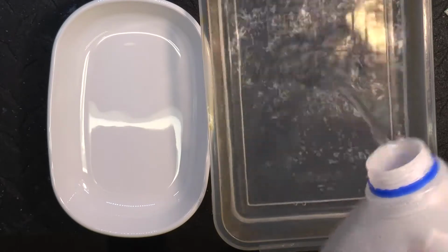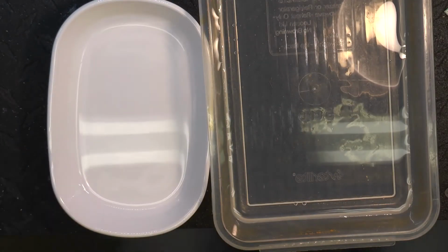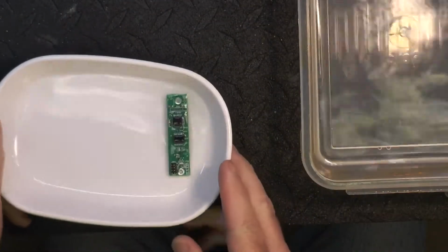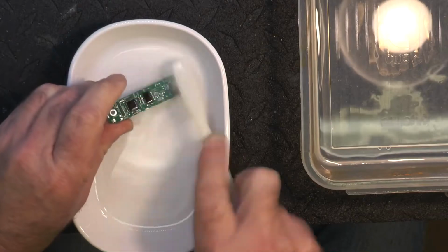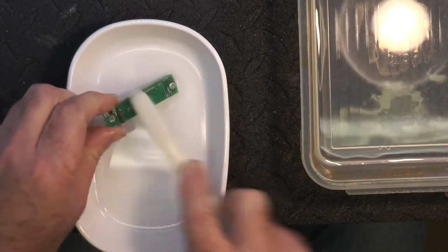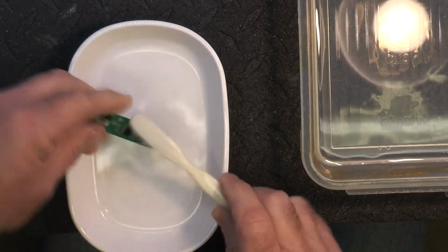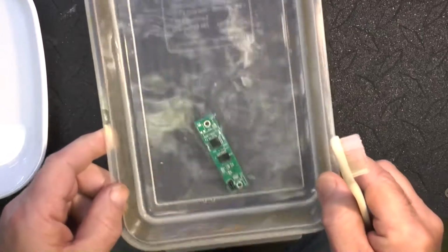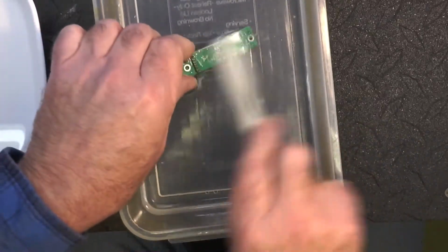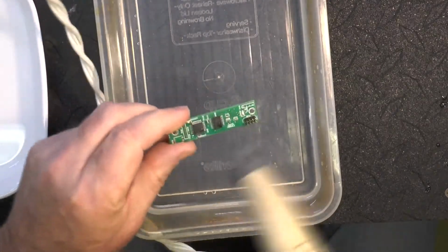Once most of the parts are mounted on the board, I'll clean it with 91% isopropyl alcohol. This gets all that rosin off that I used to mount the parts on, and it makes a nice clean board. After the alcohol, you soak it in distilled water and then dry it with a heat gun.